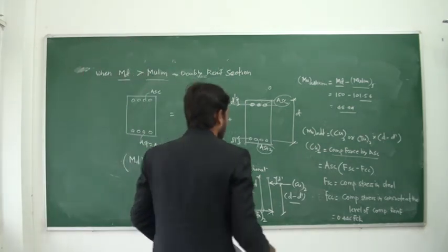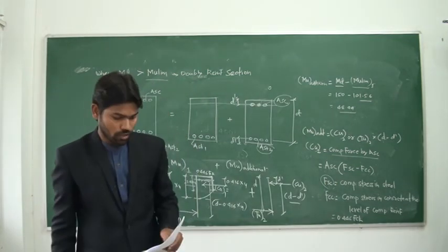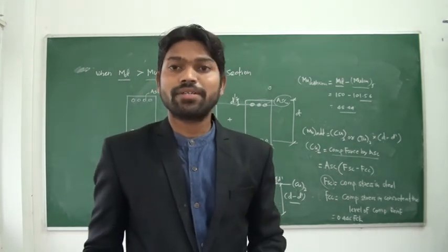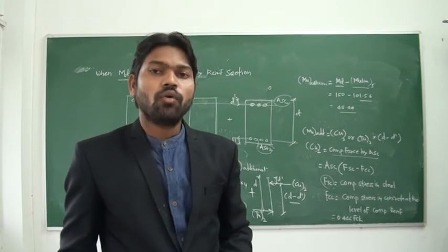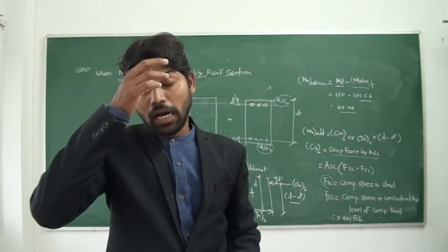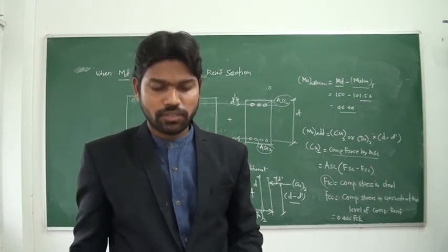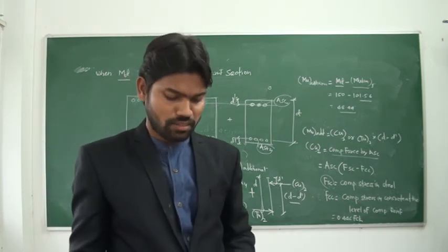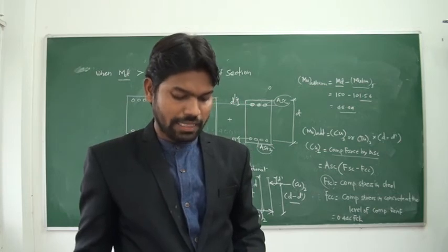Okay. So now what about this FSC value? FSC is the permissible compressive stress in steel. We have to calculate these values from the ultimate limit given for the strain, strain in concrete and strain in steel, and from that we have derived some values.